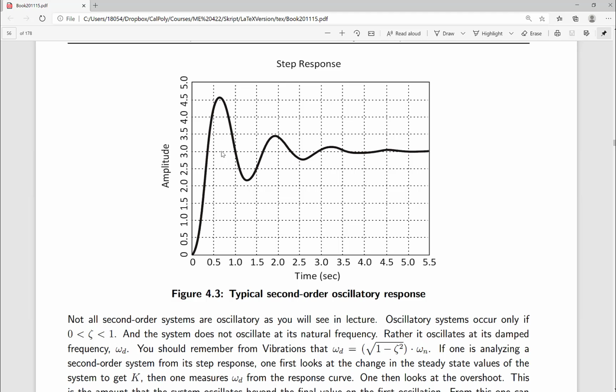The reason for that depends upon the system, but you could have, for instance, a motion system that was supposed to take a mass. It could be a robotic arm, or some kind of cart that you're moving around, and you're supposed to take it from point A to point B. Now, you have a system that's dynamic enough and doesn't have enough damping in it that when you put in the command, go from point A to point B, that's a step input, by the way, the system responds very aggressively because there's very little damping in it. So you have a large amount of overshoot because of the low level of damping.